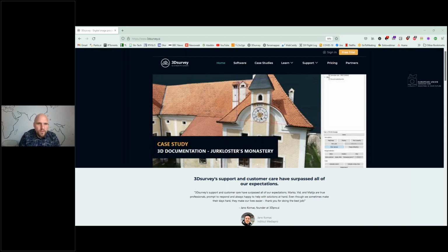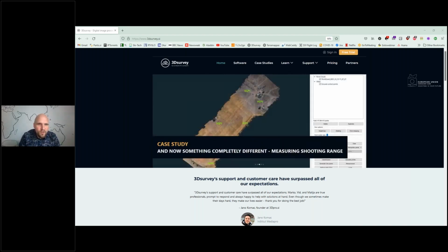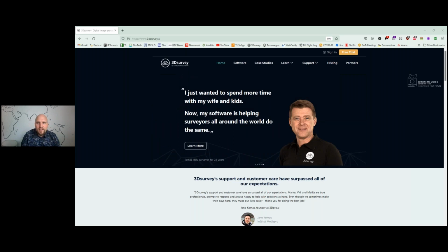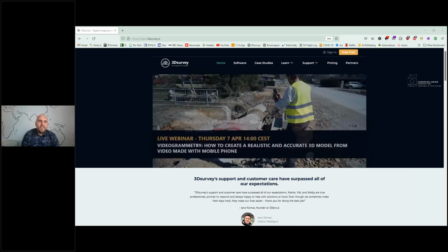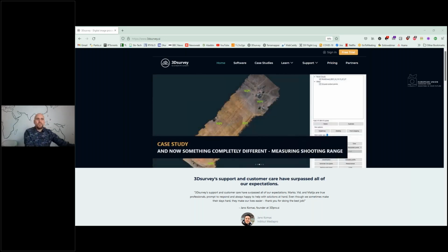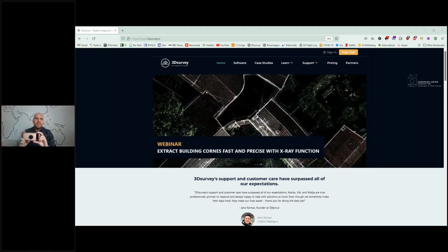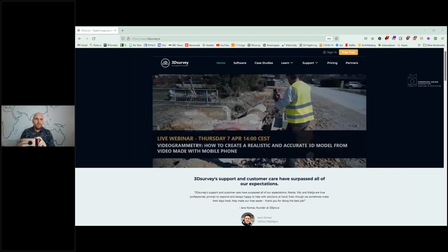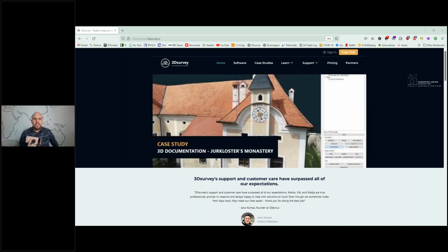The second question is from Mr. Nunez. He is asking, do you think using a manual gimbal to hold the phone will make videogrammetry more accurate with no ground control points? Yes, I think that will help, but it will mostly help indoors. That's what I found, because indoors, when you're recording with a phone, you are not holding it as steady as a gimbal would. And in low light conditions, we will get better quality data if we use a handheld gimbal. Outside, I didn't see much need for a gimbal.